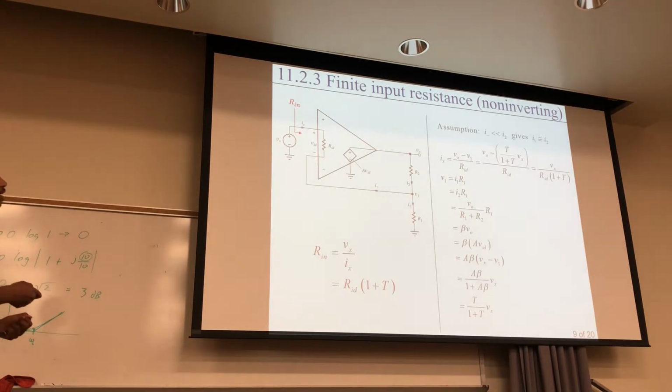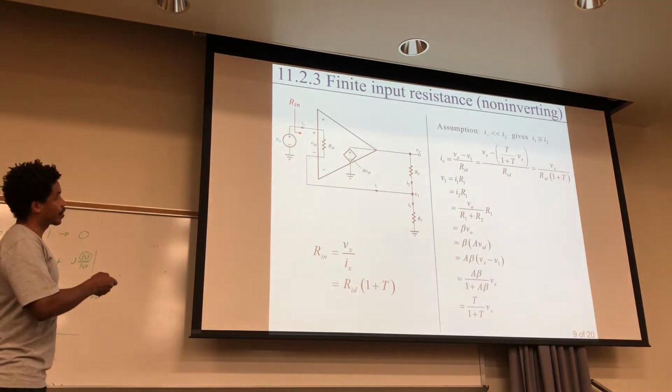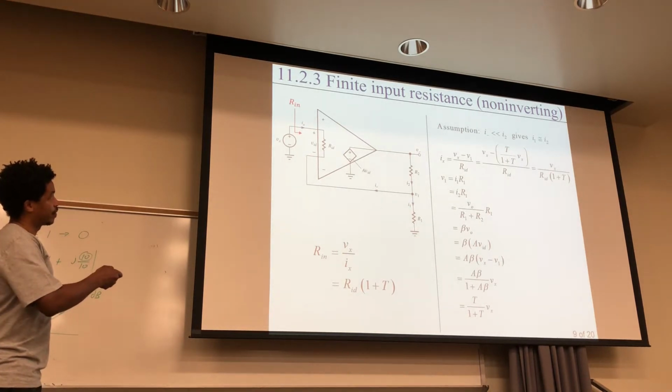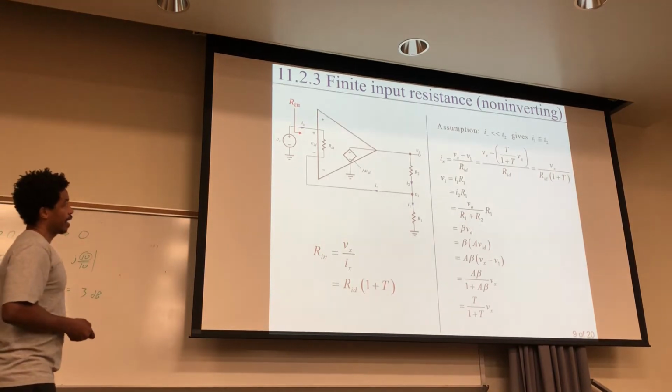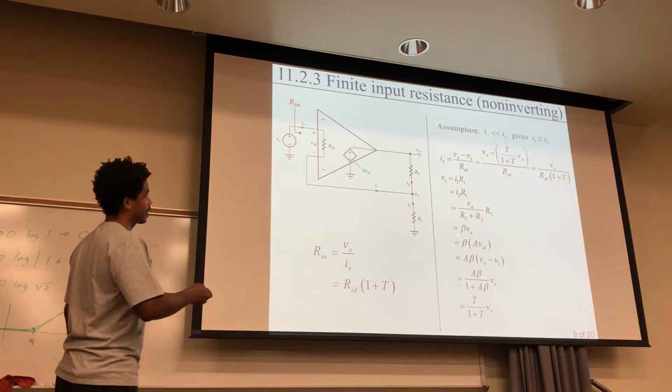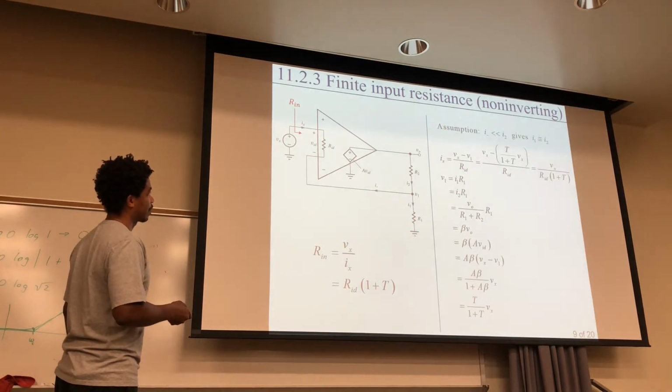Okay, you guys see that? So this current I2, which is going all the way through the whole thing, is a voltage drop from V0 to 0 divided by the entire resistance, because no current is going off in that direction. That's where we get this from. And then we'll identify this as being our feedback gain right there.